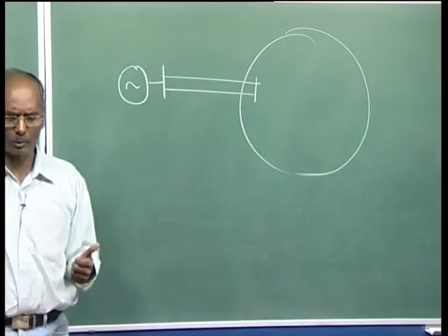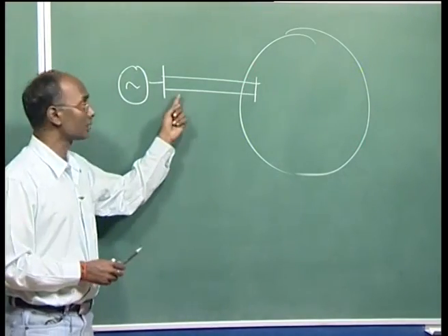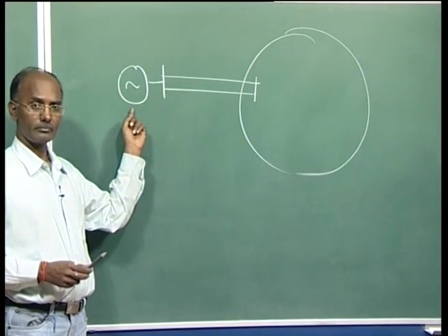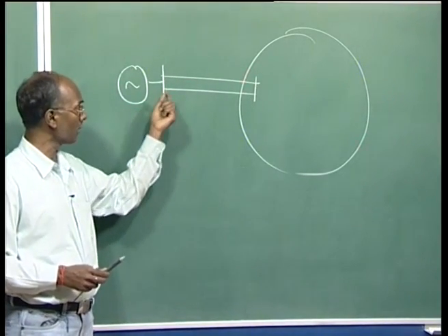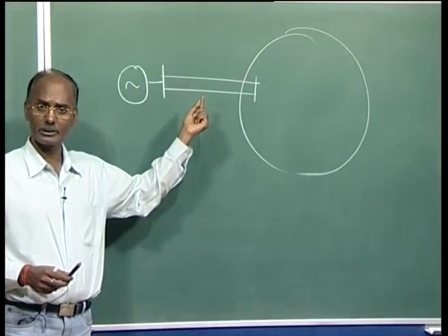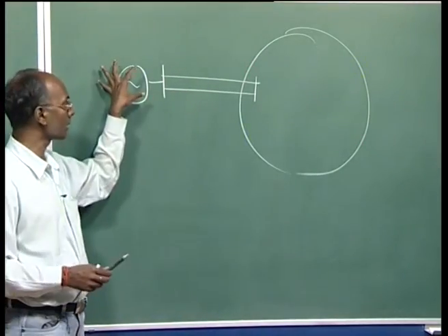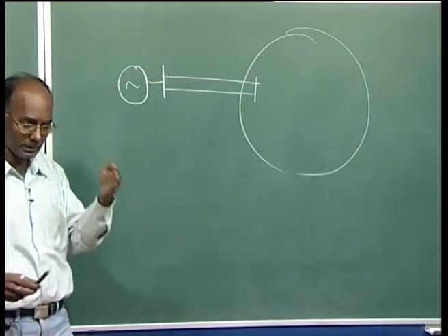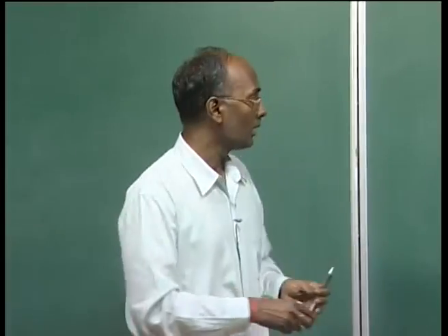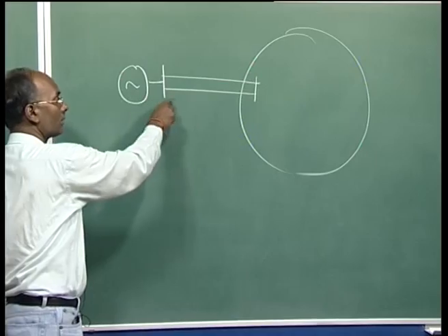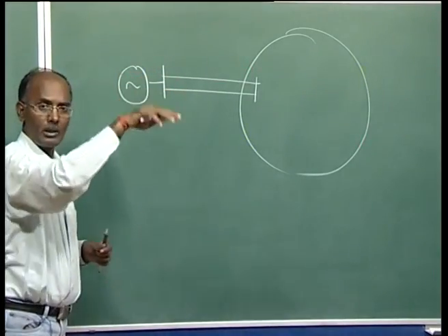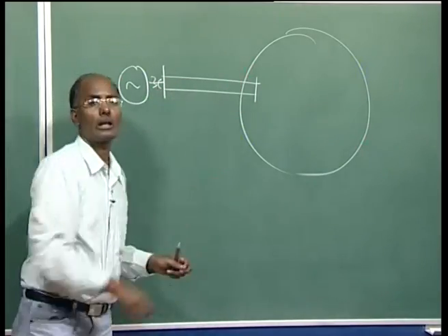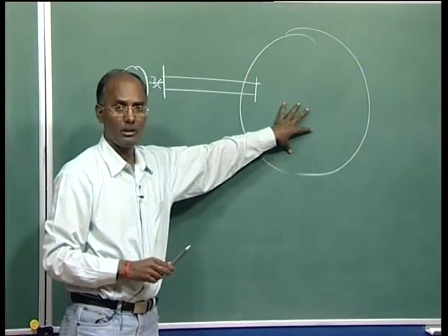So, there are some thumb rules. Also, what should be the voltage level? It is decided by the power level. Depending on the power level, we know the surge impedance loading of the lines, etc. So, the voltage levels are decided by how much power, and that is not only one unit, there are so many units at that power plant. The total capacity of this power plant decides the voltage level, and then accordingly we should have the generating transformer here, and then we can evacuate and feed the power here.